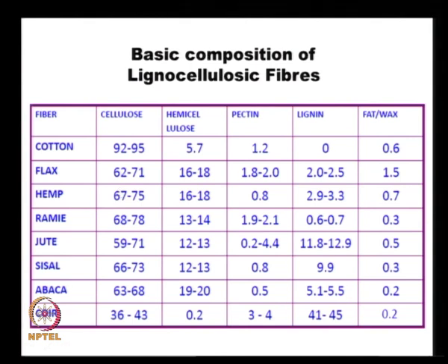So the cotton and jute are more flexible and smoother as compared to coir, and at the same time lignin gives them the life or the durability when exposed to soil or water or other environmental factors. So comparatively the coir has a longer lifespan, but lesser workability because it has a lesser cellulose content.